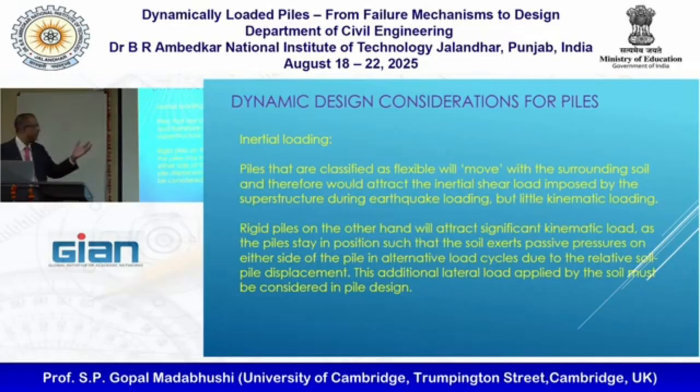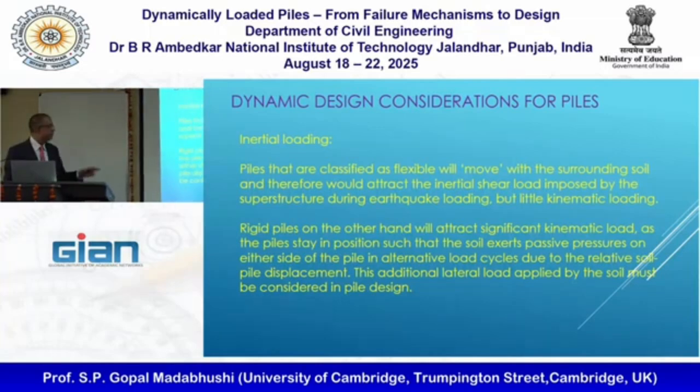So the amount of kinematic loading will be small, but you pay the price in inertial loading. Rigid piles, on the other hand, will stay where they are. So hopefully you will get less inertial loading, but more kinematic loading.